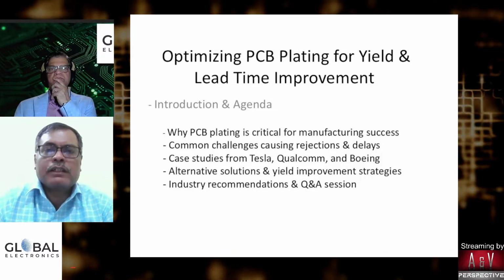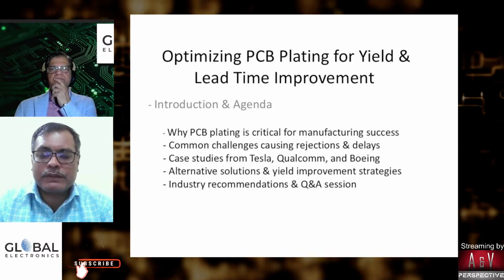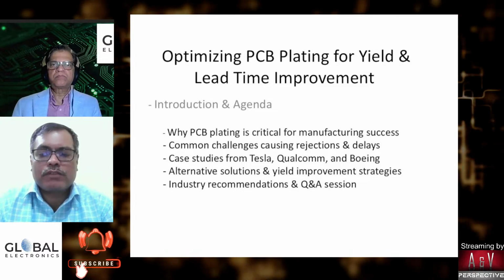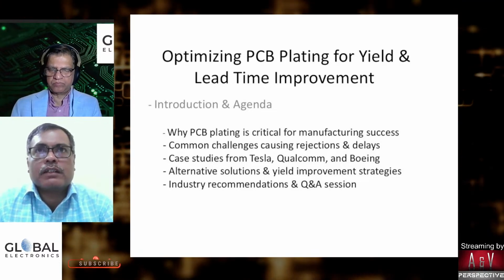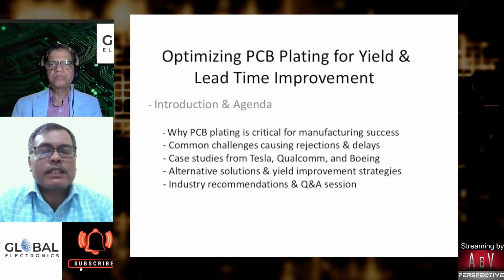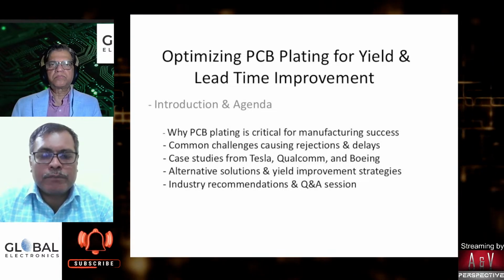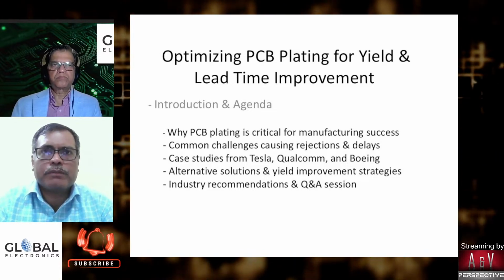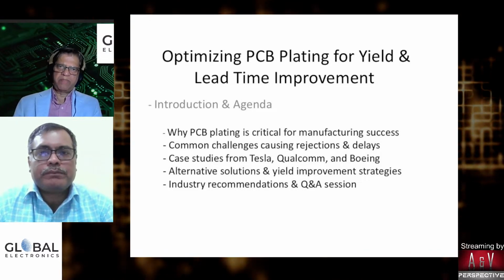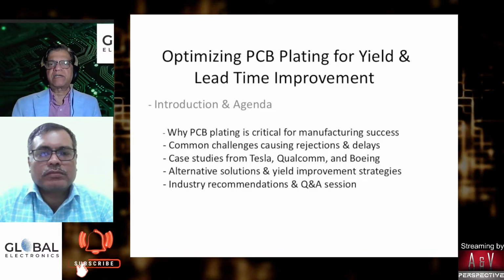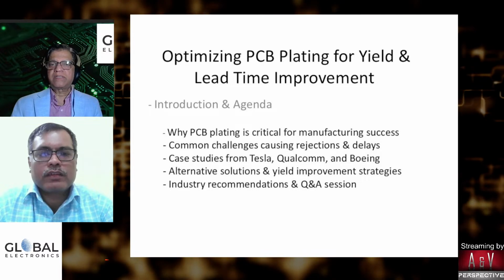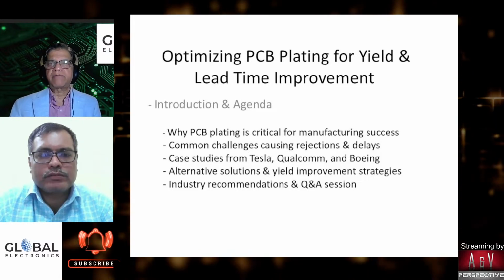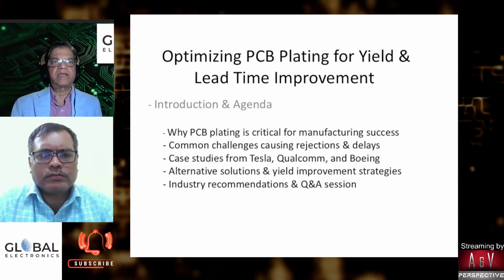And when it comes to board reliability, what happens if the right thermal gradient material is not used? Then all the reliability issues will come in the latent stages. So that has to be catered: the selection of the material and the copper distribution along the material. Many aspects will come into the picture. So manufacturability and process control play a vital role, and under process control, plating is one of the very important processes in PCB manufacturing. What is your take on the plating as such?